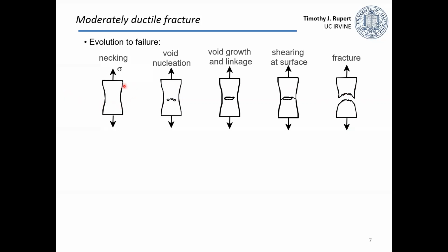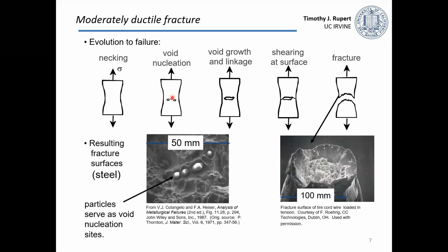Okay. So there's significant plasticity and shape change, but there's also something happening on the inside of my material. That's the distinction that I'm trying to draw here. And we can look at a fracture surface like this. This is a real life fracture surface of a metal wire. The idea here is that you can see that reduction in the overall shape, and you can also see this lip where these voids started to nucleate and grow. This is an example of how those voids can form. In this case, there were second phase particles in there that served as the nucleation sites.